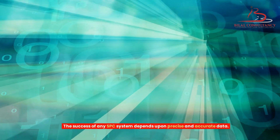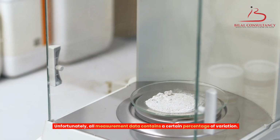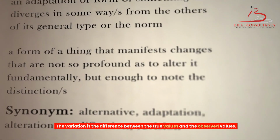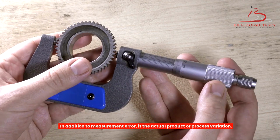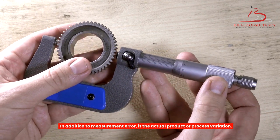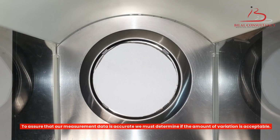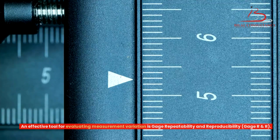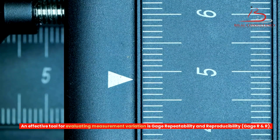The success of any SPC system depends upon precise and accurate data. Unfortunately, all measurement data contains a certain percentage of variation. The variation is the difference between the true values and the observed values. The variation represents the amount of measurement error. In addition to measurement error, is the actual product or process variation. When we combine measurement error with product or process variation, the resulting value represents the total variation. To assure that our measurement data is accurate, we must determine if the amount of variation is acceptable. An effective tool for evaluating measurement variation is gauge repeatability and reproducibility, GageRnR.